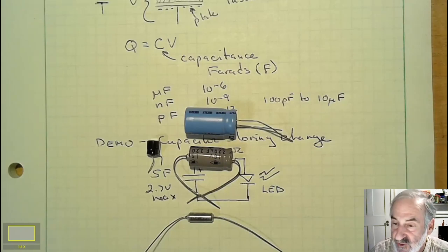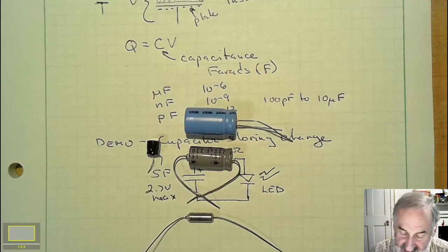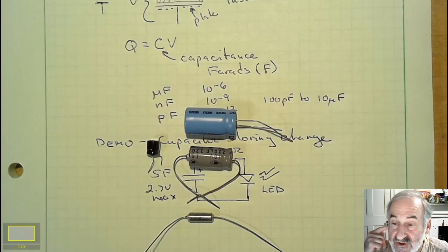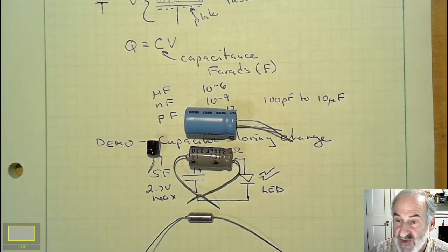There's a maximum voltage, and if we exceed that, we break down the dielectric and the capacitor fails. And of course, tolerance, which is exactly the same as resistors, except that capacitors tend to have looser tolerances. We typically use plus minus 5% resistors. A plus minus 5% capacitor would be unusual and expensive. Our capacitors are typically plus minus 10, plus minus 20.